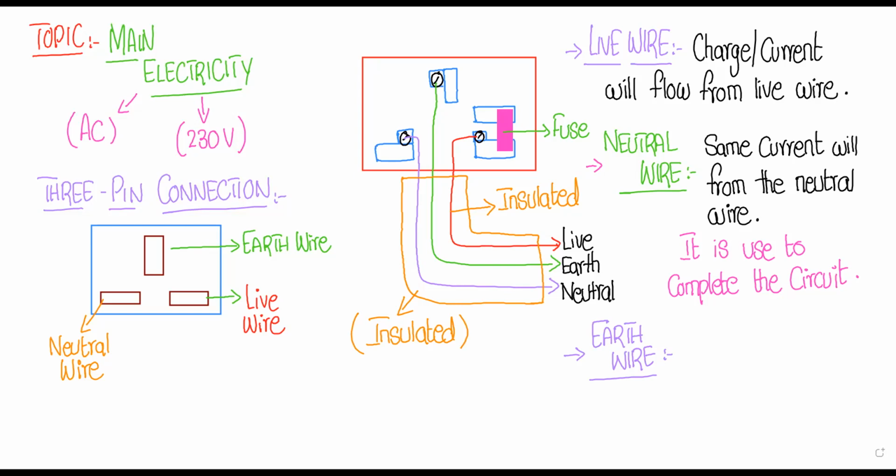If you try that, we break the top pin of the 3-pin plug, this one, and we just fix the live and neutral wires in the circuit, because a 2-pin plug is available everywhere, but 3-pin is not available everywhere, right?